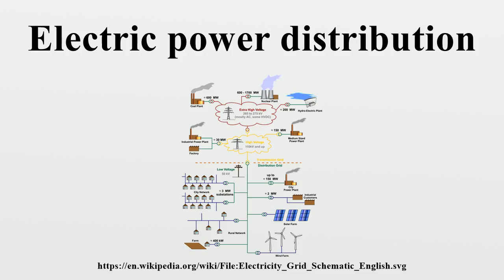An advantage of the North American system is that failure or maintenance on a single transformer will only affect a few customers. Advantages of the UK system are that the transformers are fewer in number, larger and more efficient. And due to the diversity of many loads, there is reduced waste due to there being less need for spare capacity in the transformers. In North American city areas with many customers per unit area, network distribution may be used, with multiple transformers interconnected with low-voltage distribution buses over several city blocks.